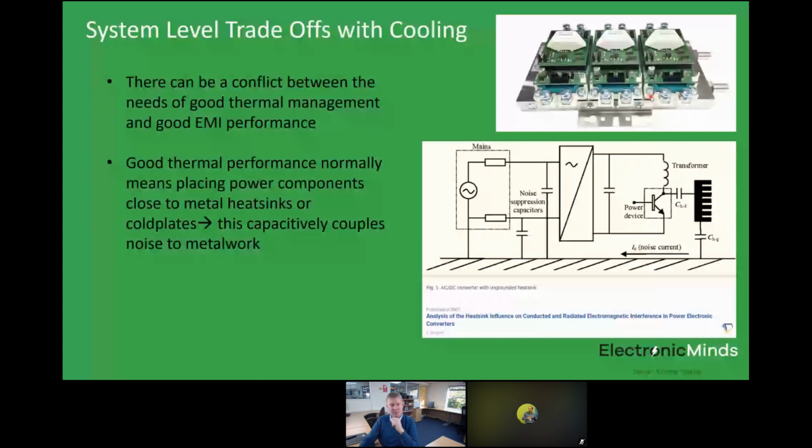And therefore, we're going to be injecting a lot of capacitively coupled noise onto that cooling plate. Now, if that cooling plate is earthed, really what you're doing is pumping a load of high frequency common mode noise into earth, which is an EMI disaster. So you can see why in that application, we've got a conflict between thermal design and EMI.